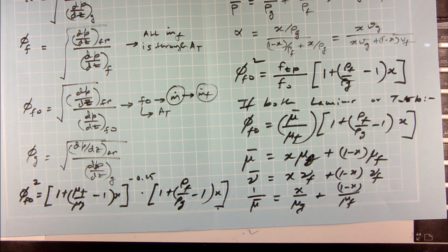Your velocity of the gas phase is going to be higher typically than the velocity of the liquid phase. So, in that type of situation, people use what is known as a separated flow model. And then the other part is the void fraction, which I will come to a little later.